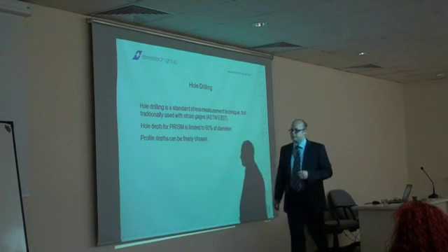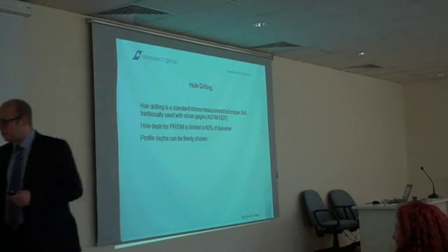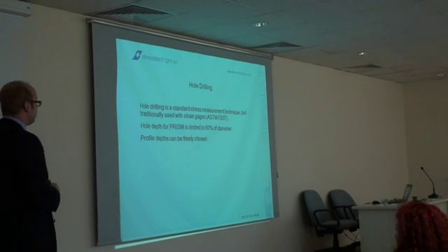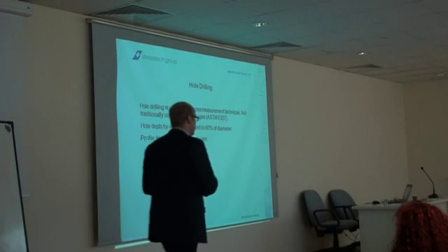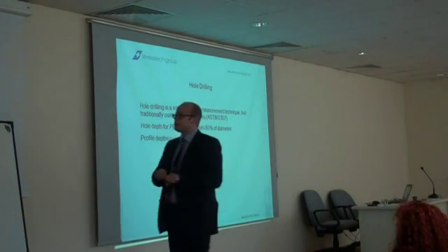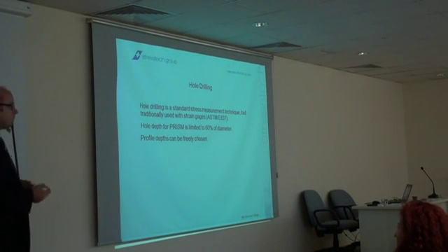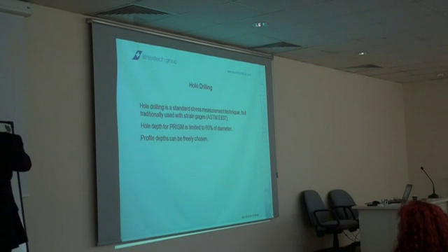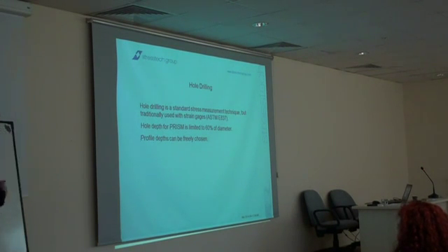And yesterday there was a good question: are we comparing the results of X-ray diffraction and hole drilling? Of course we are, because we have both methods in our house. But as I already said yesterday to some of you, it's not so straightforward, because when we make measurements with hole drilling, for example, this is the first step, 25 microns. With X-ray, we take maybe from the surface, and the penetration depth is 5 microns, which means that this is the average value from the first 5 microns. And with hole drilling, this is the average value from the first 25 microns.